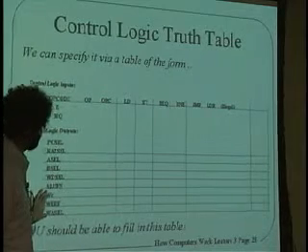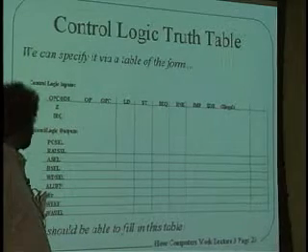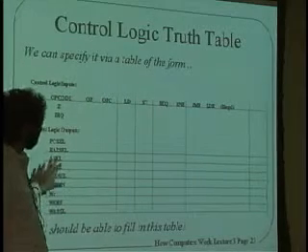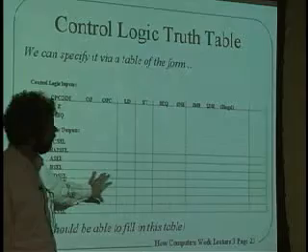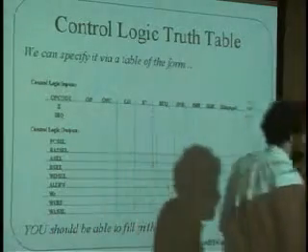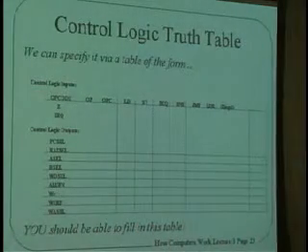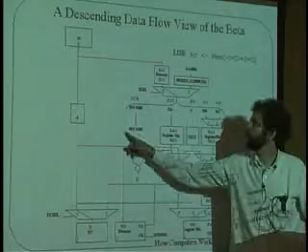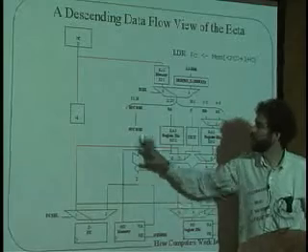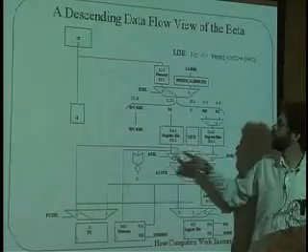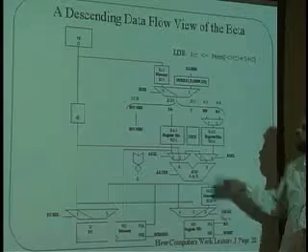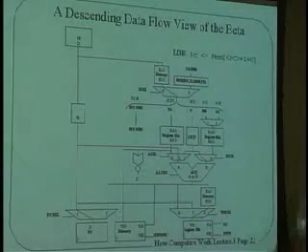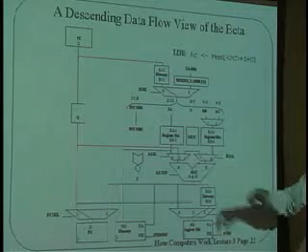And then the write enables that go to the 3 files down at the bottom will also depend on what we're trying to do. In all of those cases, you can fill in a table here that fundamentally is taking, in this picture, an indication of what is the opcode, what is Z, and depending on those things, what each one of the other control inputs to the selectors and to the E inputs down here should be, whether they should be on or off, what path they should choose.